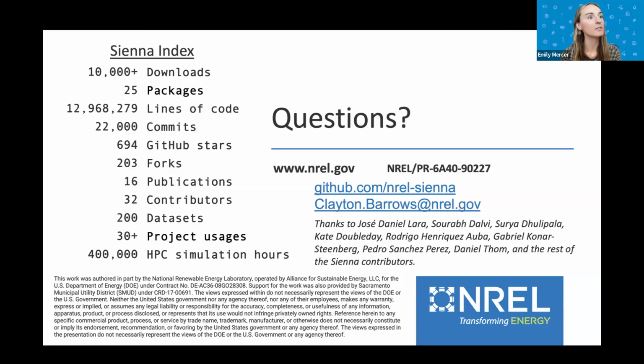All right, next question. Could you expand more on any support for moving between or across timescales within the context of a single study? So I think that it is fundamentally challenging to move between planning and scheduling, and between scheduling and response timescales, and thinking about those large groupings that I described earlier. We have addressed some of the challenges by simply holding the data in a coherent way, and so we can now hold a system data set that represents different expansion options and the systems that exist at different times, and the dynamic models associated with all of those assets within a single data set. So that's one aspect of the challenge.